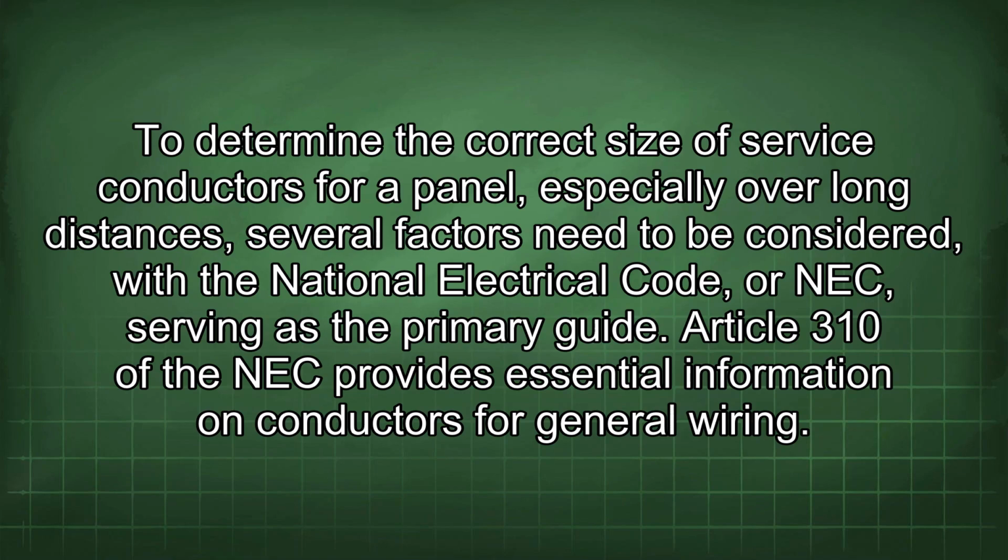To determine the correct size of service conductors for a panel, especially over long distances, several factors need to be considered, with the National Electrical Code, or NEC, serving as the primary guide. Article 310 of the NEC provides essential information on conductors for general wiring.